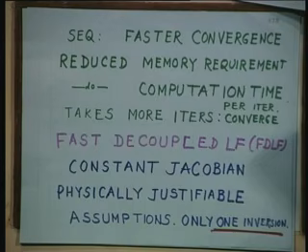He was not quite happy with only decoupled, right? What was the need? So the Jacobian becomes constant, and once your Jacobian becomes constant, you have to invert it only once, because in every iteration no changes take place. Once it becomes a constant matrix, there is no point in inverting it again and again. You are still going to get the same answer.